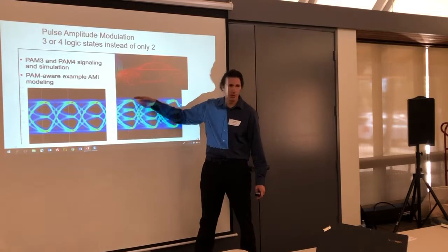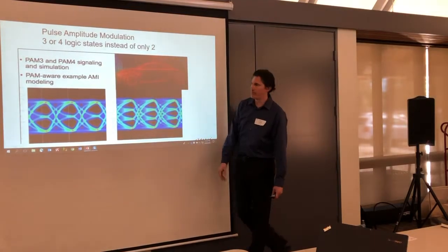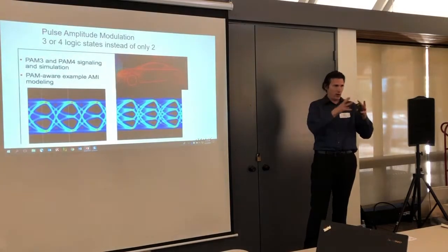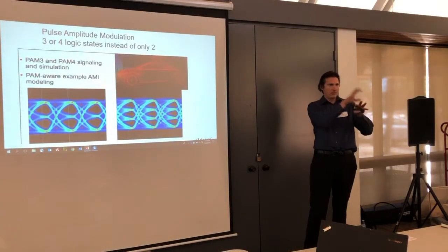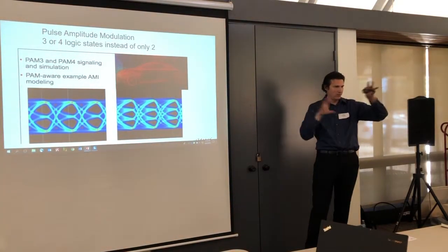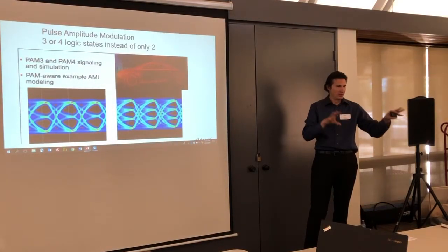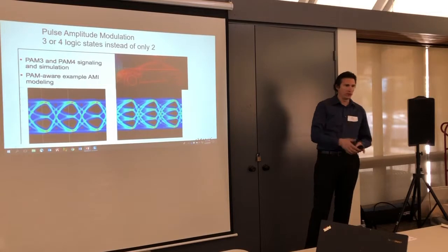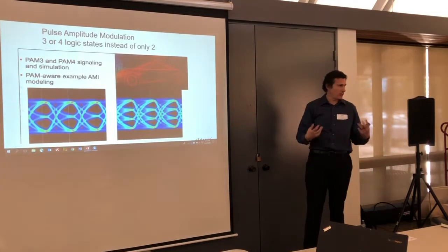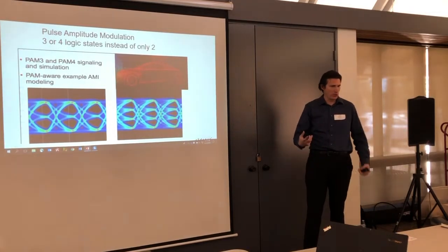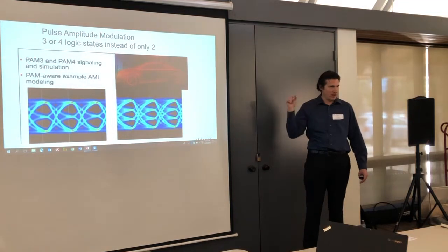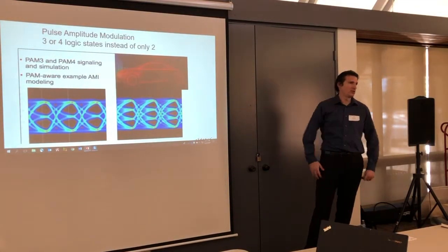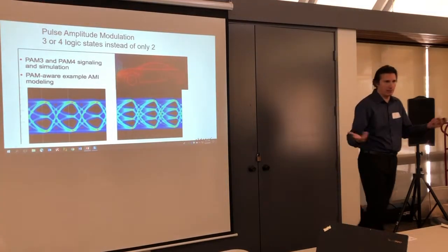So this is popular in the automotive industry because they're having to transfer a ton of data from different portions of processors in the vehicle and out of the vehicle to wherever else it needs to go, and just single ones and zeros wasn't cutting it. A lot of it also because automotives are super, super noisy, and they're using the cheapest twisted pair cable all over the place. A lot of it they're doing just for redundancy. Let's send the same data twice and then compare it at the end to make sure everything's in place.